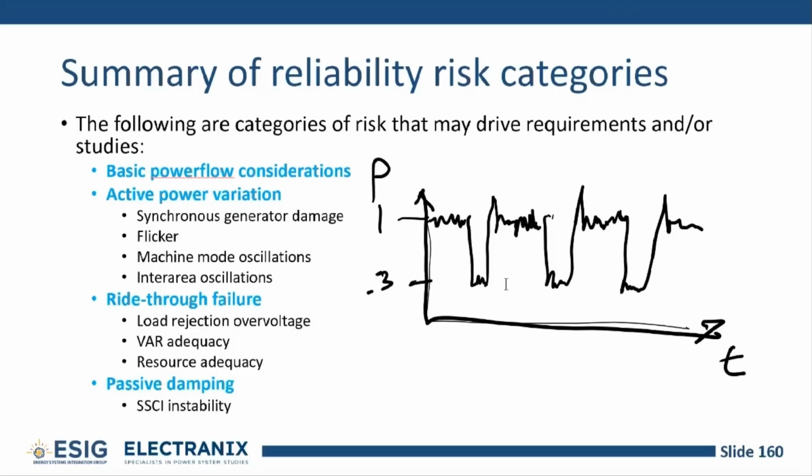But you said measured, so you got this kind of data measured. Yeah, we've seen measured, and actually some has been published now. You can see various sources of published data that show it. Sometimes these are test power. A lot of the data centers that are coming in are under construction to greater than a gigawatt, but we don't have any that are that big yet. We have 200 to 300 megawatt and bigger. The ones coming in at 1,000 will have test power at 30 to 100 megawatts, let's say. But it's just a complete scaling factor. It's going to be exactly the same profile.